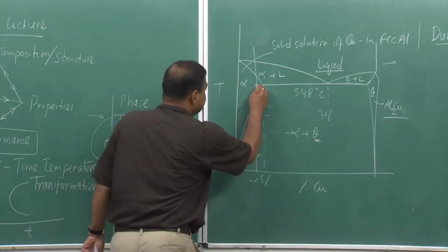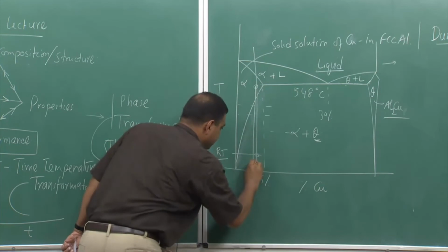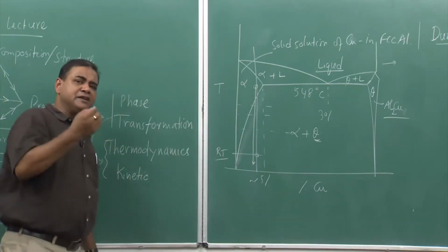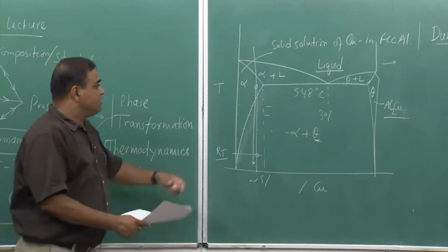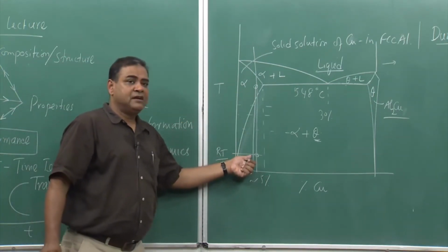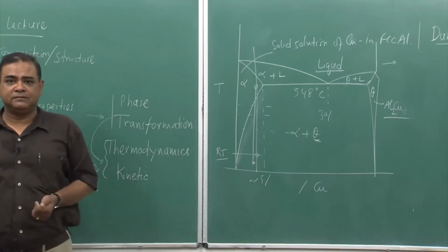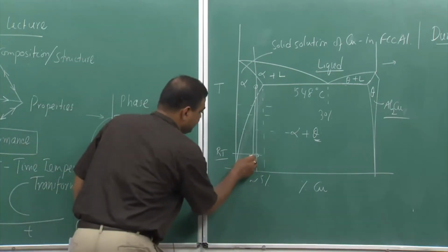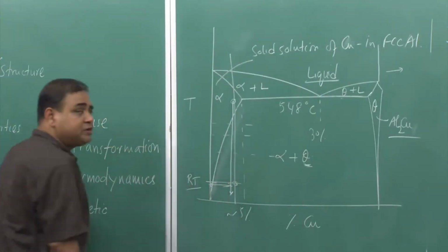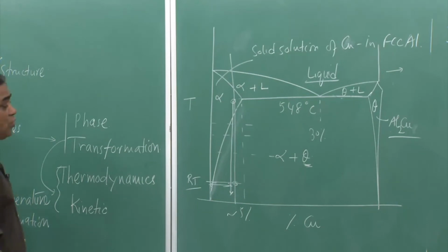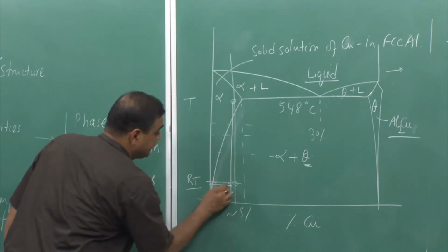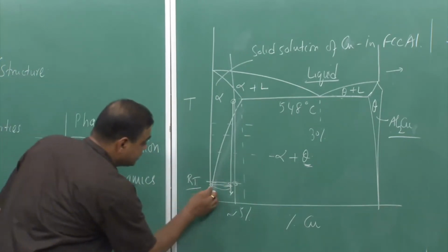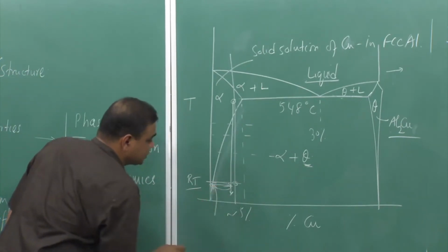Now, after that, if we quench it quickly to room temperature, we will have a little increase in hardness, because quenching leads to entrapped copper in the solution, but at this temperature the system does not like to hold that particular amount of excess copper. So, this is my excess copper, and the actual equilibrium percentage of copper in solution is this one.